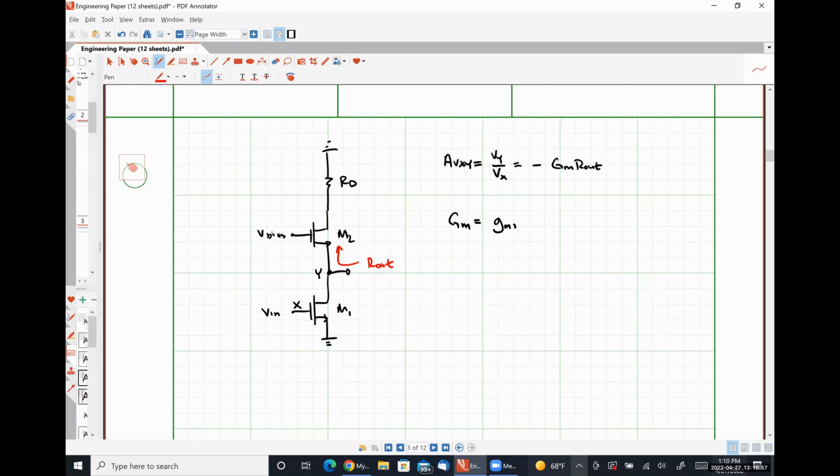Now, the reason for that specifically here, because I saw some of your heads do a swivel, is because we're neglecting channel length modulation, right? If we did not neglect channel length modulation, we definitely have an R out looking down, and then we'd have something different looking up. Because we've been neglecting channel length modulation, though, what we see down is an open circuit. What do we see up, neglecting channel length modulation?